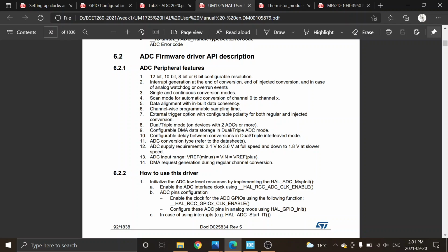So in the ADC, I could want faster. There's so much per bit that you could get in resolution. So I could give up some resolution for making my conversions happen faster. Or I can go all the way up to 12-bit. Do you know on the PIC, what did you guys have? Was it a 10-bit, an 8-bit? What did you go up to as far as, was it 1024 or something like that? Okay, and so we're 10, so this is going to give us a 12-bit.